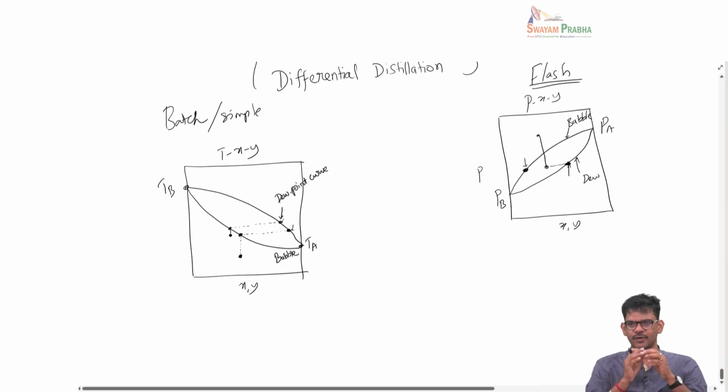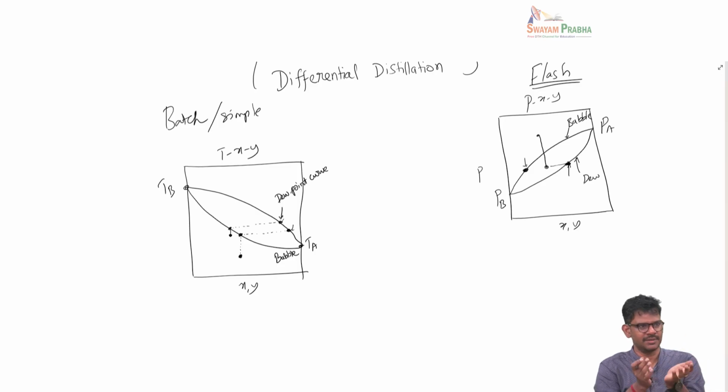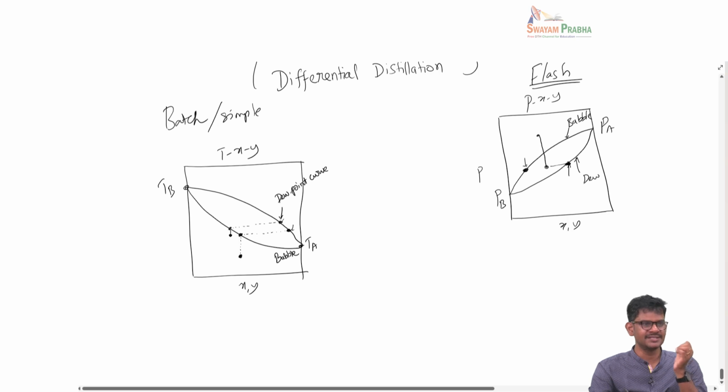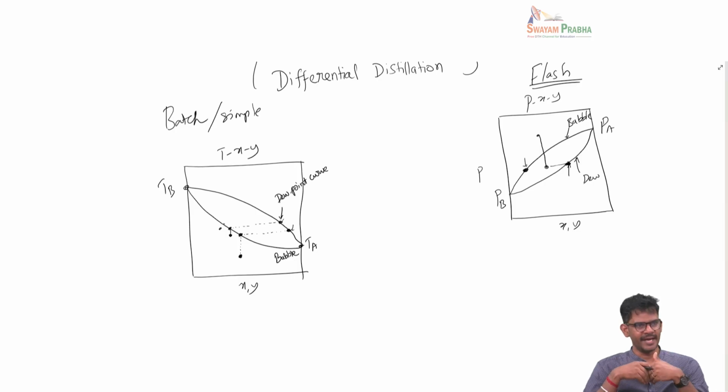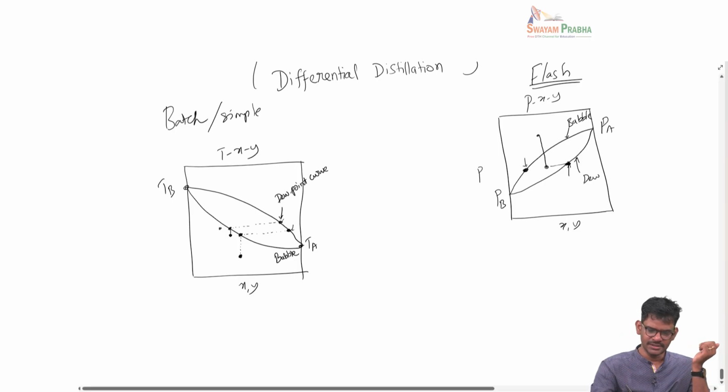reservoir. Now with respect to the still, the distillation column that I am talking about, the composition would now be lesser than this point, because some amount of vapor has been removed, some amount of A is taken out. Okay, so it moves somewhere here. At this point again I am below the bubble point, and I have to supply heat and increase this temperature to the bubble point temperature here, and again I have another flash, right? So I can keep on doing this multiple times.